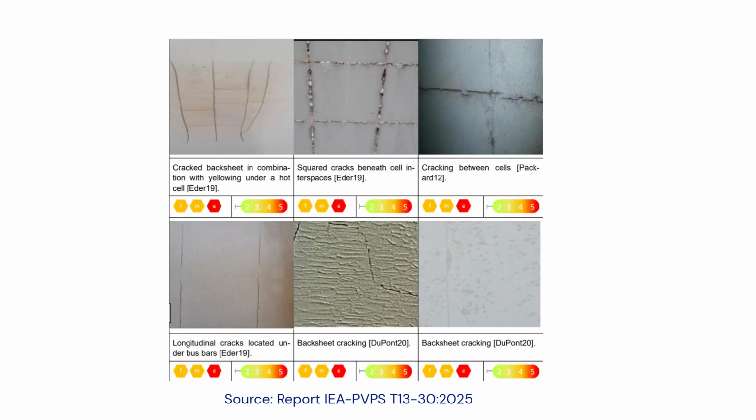Any damage of the backsheet, surface or whole stack, that is visible as crack, burst or scratch. The location and extent of the cracks depend on the cause and progression of the failure. The cracked area may be localized, like bursted bubble, scratch, extend along specific module areas, like along or between the cells, along the bus bars, or extend over large or the full area of the module, like embrittled surface. The crack can be very deep and affect the backsheet stack.